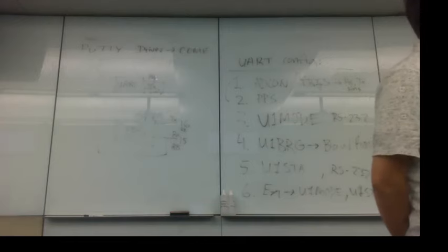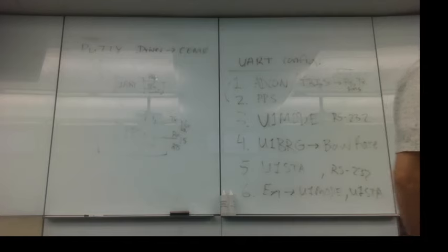It would push 2 word locations, so it would do 32 bits. So it could be that when you do move.d W15 minus W2, it does W2 and W3 at the same time, and then move.d W15 minus W0, it does 0 and 1 at the same time because it's doing 32 bits. I'm not sure. I'd have to look at it. So as you're pushing, you have to push W. Yeah, you would do 4 things.